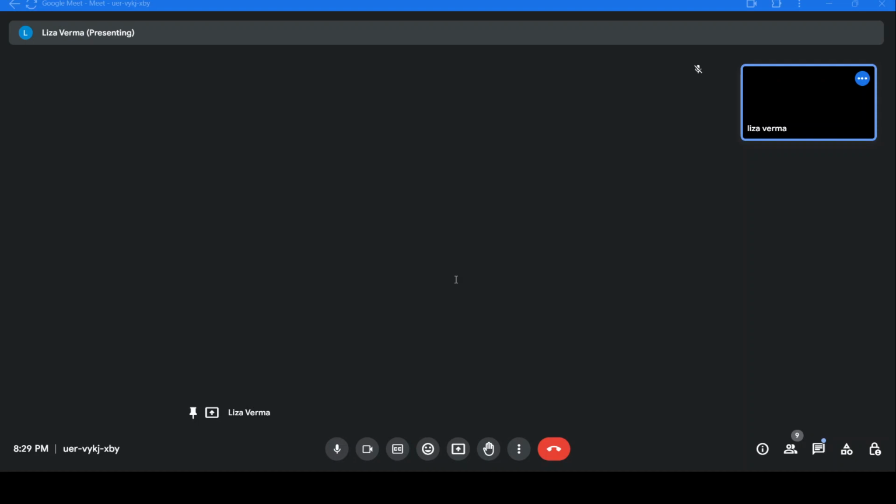So what is the doubt? Correct answer is not acceptable, or any of the other options? So the answer they had given is D. Answer D. So D is: the program's first return instruction may appear before the first call instruction. Yeah, that's possible, right? Because RST 0, the vector location is 0000. I can very well have one return instruction inside that 8 bytes.